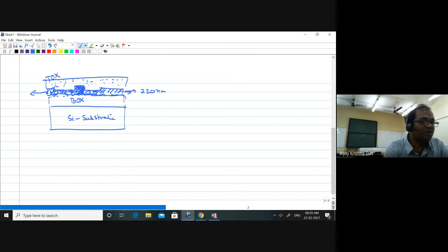You can consider, but because it is silicon and refractive index is 3.45 or so for 1550 nanometer, you can design this cross section in the order of submicron, in the nanometer scale. So 220 nanometer height, and in the horizontal direction you can consider 400 nanometer or 500 nanometer, then that is sufficient to confine light inside the silicon, and that can be considered as a core of a waveguide. Okay, that is called rib waveguide. And if you are completely removing, then it is called photonic wire waveguide.